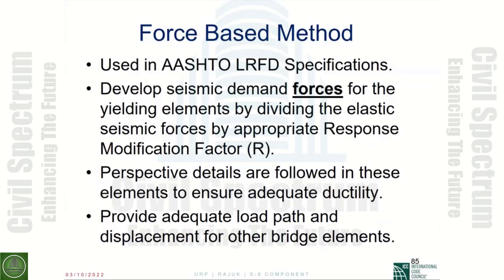You need to provide details for that, and we have implied details. We don't tell you how you are doing that, but we tell you what will be the minimum confinement steel, the minimum reinforcement, all of these things that you will be able to really guarantee what will be the ductile behavior of that element.